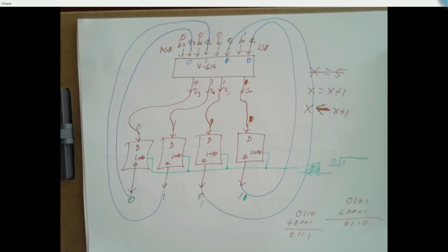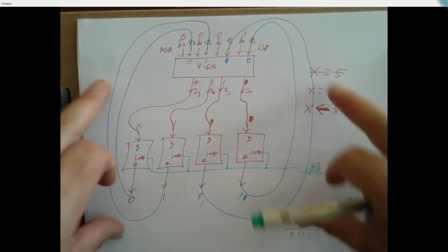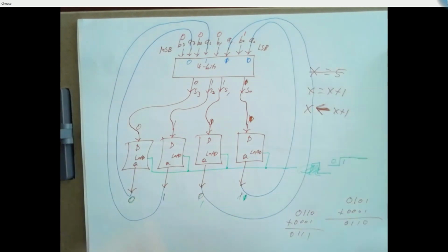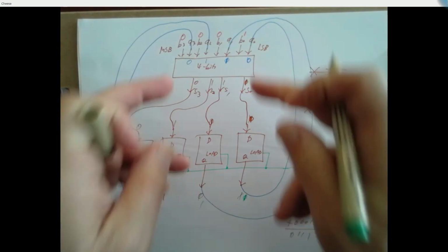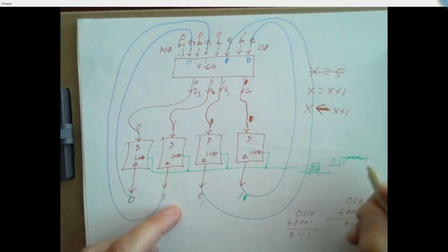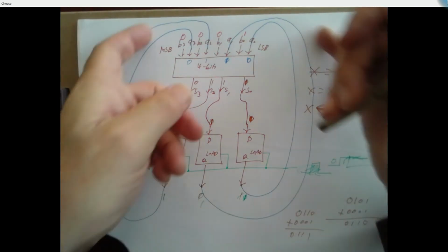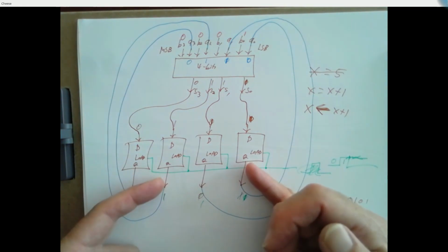But the circuit that we've built is basically saying keep adding 1 to X. So one way to fix this is as soon as this 6 has gotten loaded into here, slam that load line down. Set it back to a 0 quickly before that 6 can come around, turn into a 7, and get loaded in here.